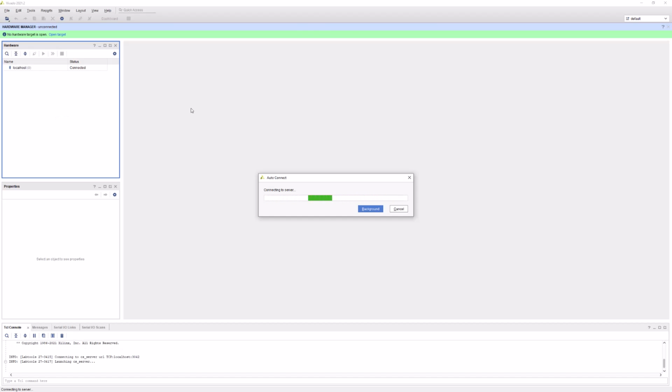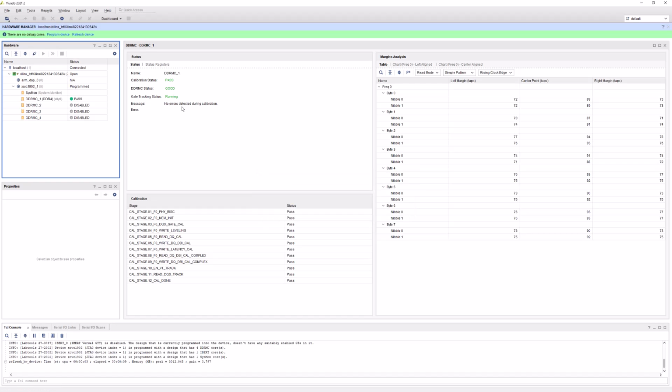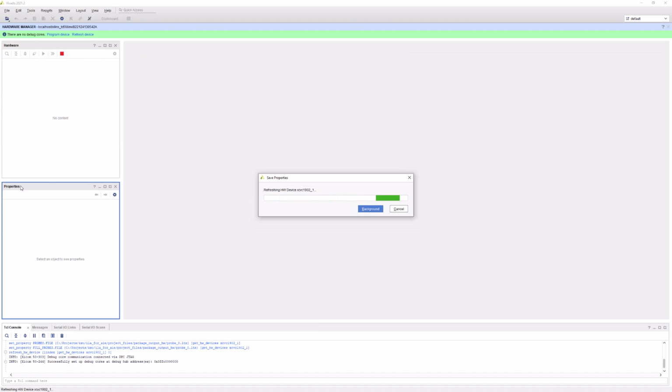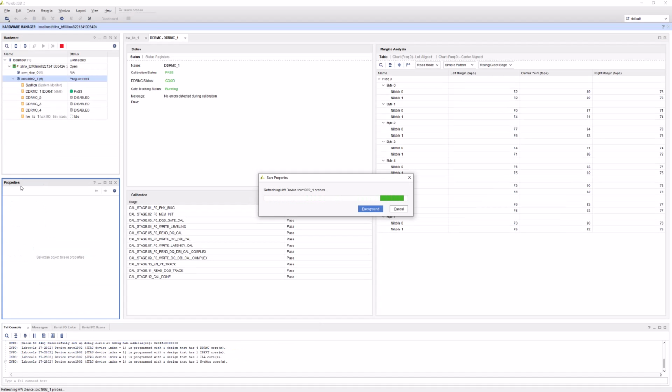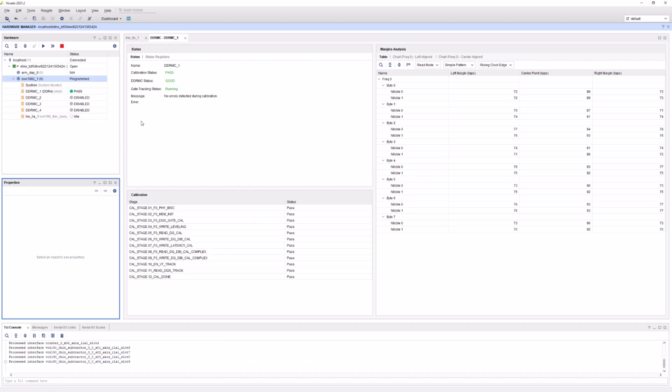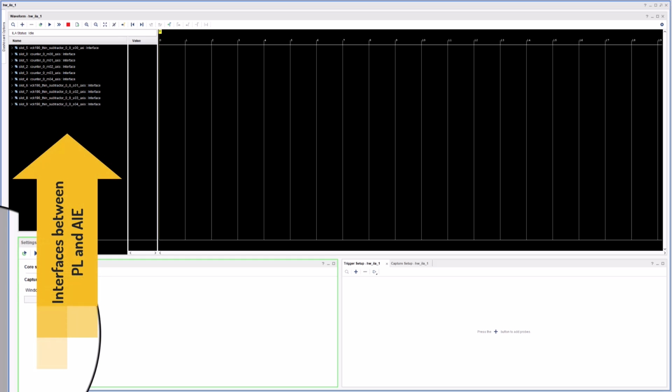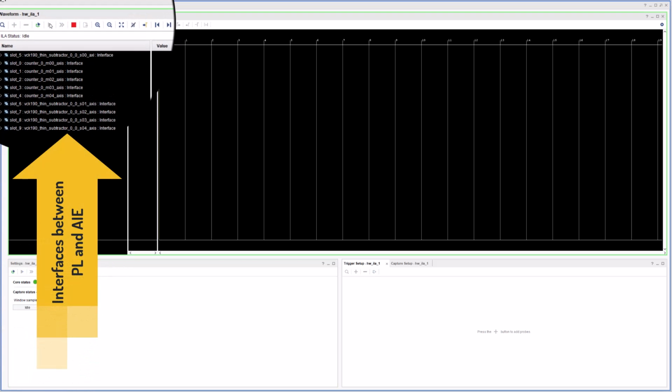When the hardware project containing the ILA was built, a probes file with .ltx extension was generated. Selecting the Versal part, then going to its properties box and specifying that probe file will open the logic analyzer after refreshing the hardware link. You can then go to the tab and open the logic analyzer. Now that we're connected to the target, the ILA can sample the selected signals.